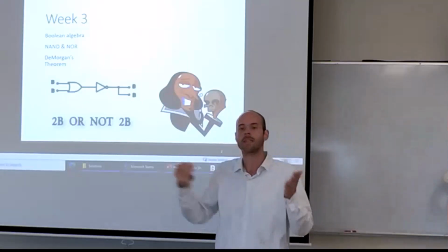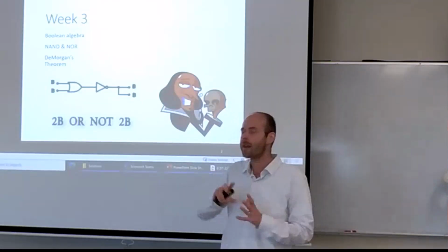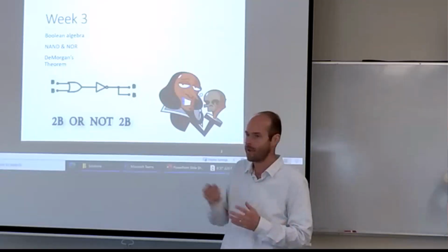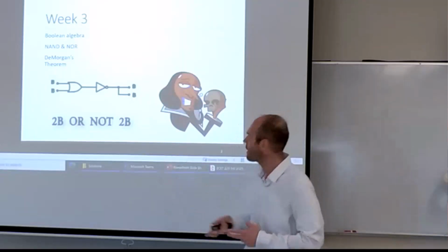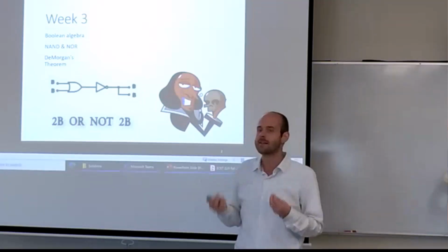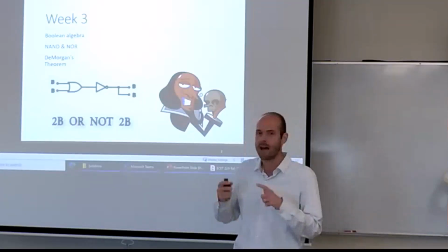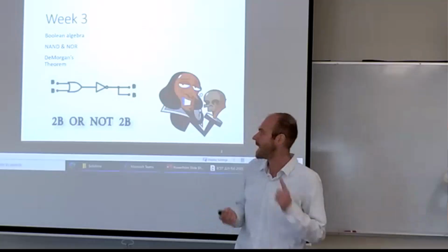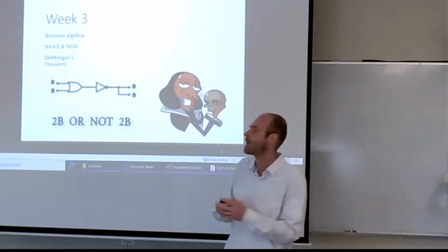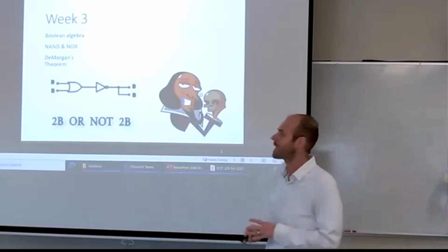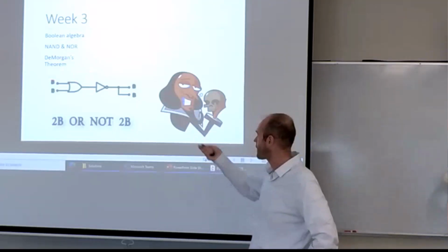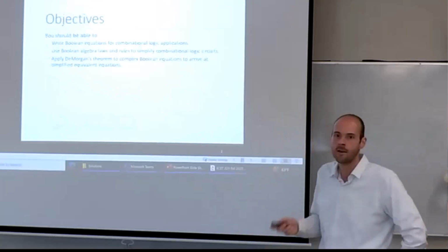So you'll see a lot of logic made entirely out of NAND gates. And so what we're going to talk about today is how to build other pieces of logic, other gates, out of just one kind of gate, for example. And the Boolean algebra will let us sort those around as well. But that gives companies and engineers the ability to design one really good NAND gate, rather than having to design a really good one of each kind of gate, and use that to make everything else. Then we'll look at the rest of these algebraic related laws.